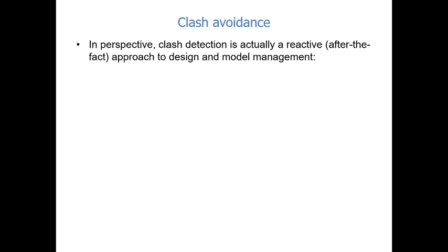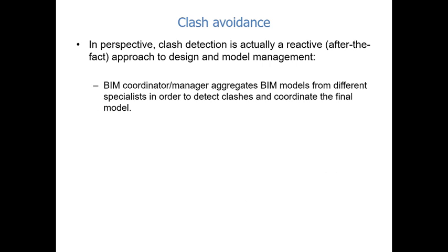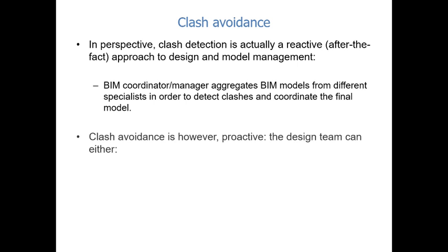However, as I said, clash detection is reactive to design model management. The BIM coordinator manages or aggregates the BIM models, okay, from different disciplines in order to detect clashes and coordinate the final model, right? Clash avoidance is, however, proactive.